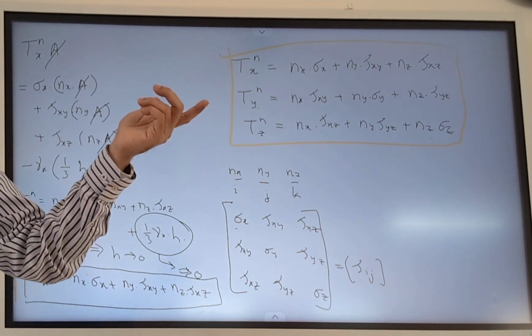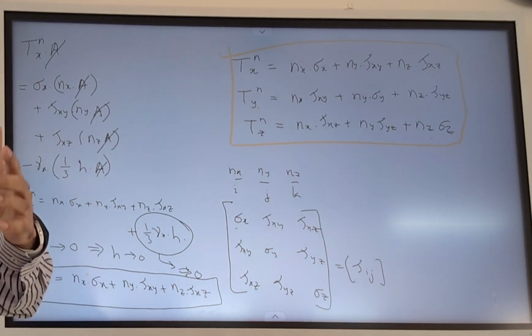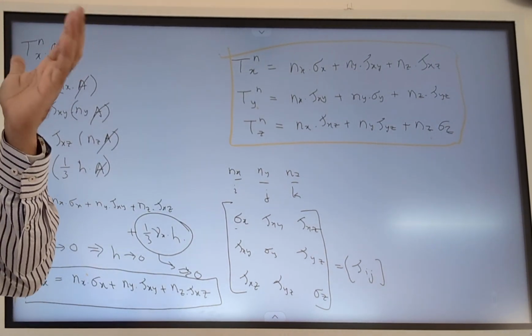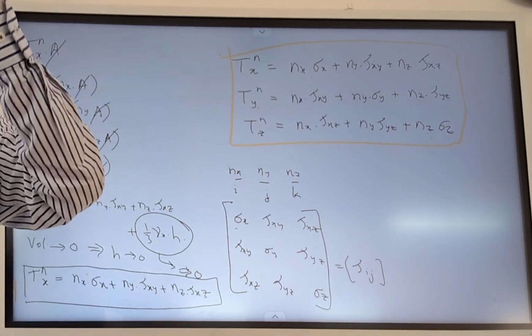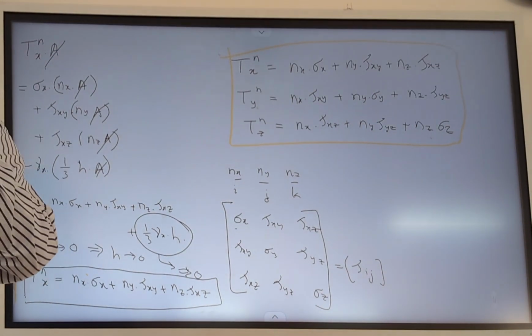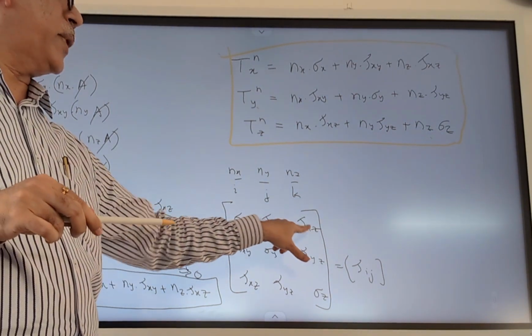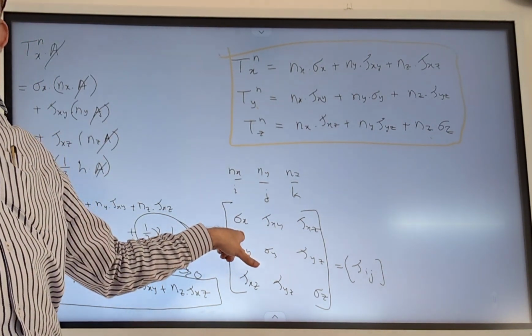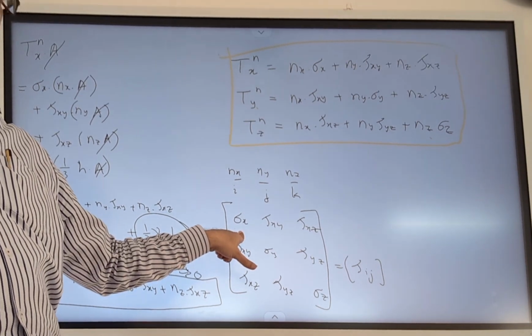In actual engineering design, you will use it to calculate which is the critical plane. You know that this particular component is pulled in this direction, subjected to torsion, subjected to bending. So it will lead to some three-dimensional stress state. These components can be calculated using the ordinary axial stress formula, bending stress formula, and torsion shear stress formula.